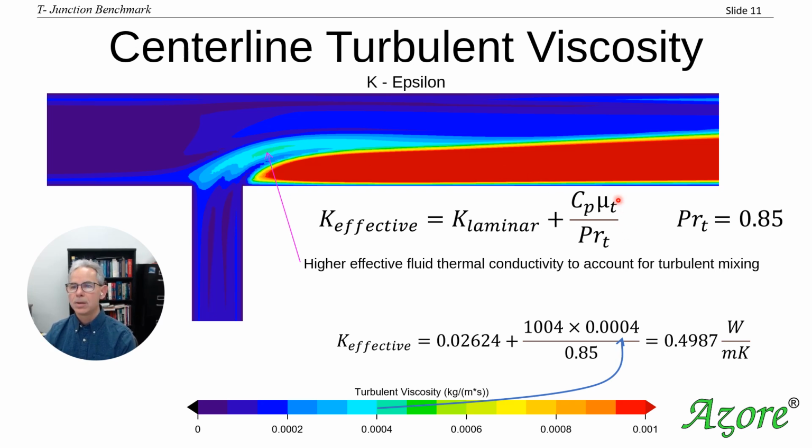And so it makes a certain amount of sense right here that when our turbulent viscosity is high, then our effective viscosity is going to be high. But likewise, when this value becomes small, then we kind of trunk down to just the laminar representation. Having the specific heat in there also makes a certain amount of sense, because the specific heat really represents